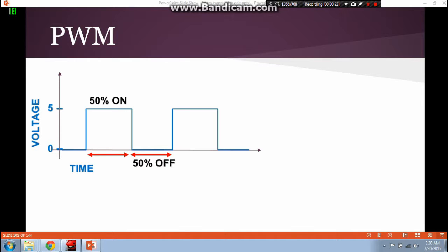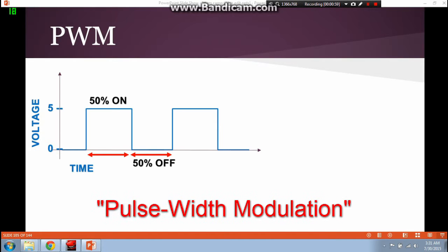And so what we know about our computer is that our processor is capable on these digital, there's a reason they're called digital output pins, right? That's because they can either supply 5 volts or 0 volts. They can't do anything in between, right? Because of the digital nature of the processor. So a way to simulate outputting analog values is to use what's called pulse width modulation. And it's quite what it sounds like, and it's really a pretty easy concept to grasp.